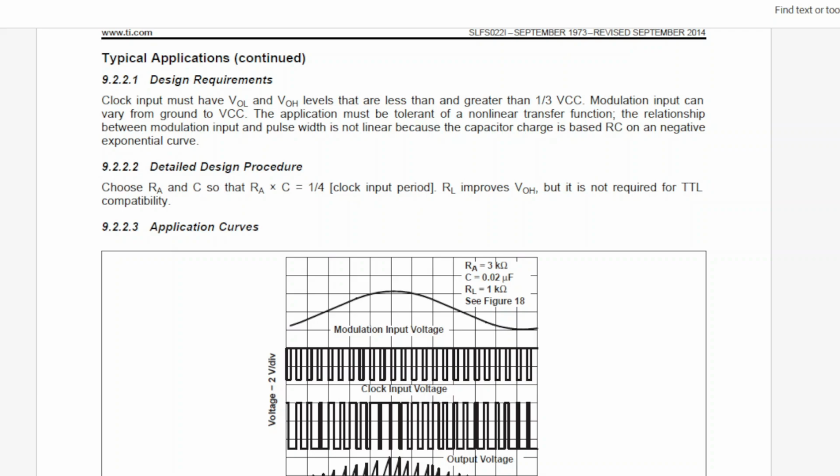Now the problem is the pulses don't seem to change a terrific amount, and the gaps do a little bit, but it's not how I'd want to do the pulse width modulation. I want more control over it, and this doesn't look like it's going to give it to me, so I discounted that and didn't even bother going any further than looking at the data sheet.